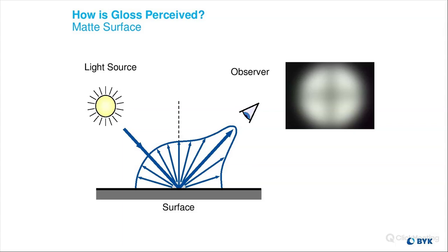Another one here. How often do gloss meters need to be calibrated? Well, the typical interval for calibrations is about a year, 12 months. Sometimes we go out maybe 18 months. The instrument itself does come with a polished black glass, so that when you turn the instrument on, it'll tell you to calibrate, and it'll self-calibrate itself.